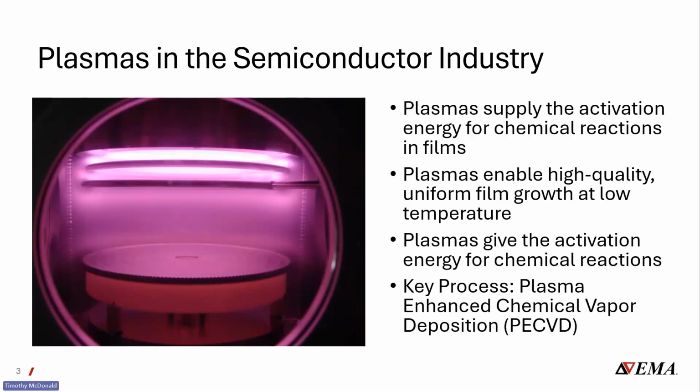Stress engineered films are another consideration. PECVD enables tuning of dielectric stress to strain silicon channels. This has been used since 90 nanometer and smaller nodes for mobility enhancement in those particular channels.